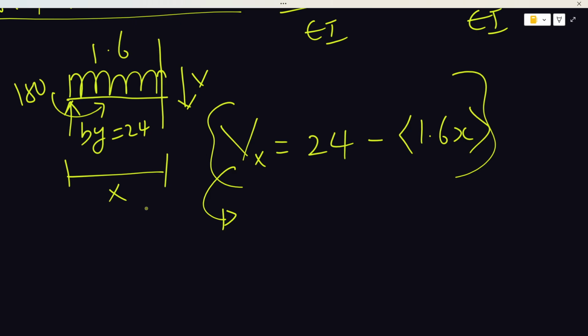So it means that we're saying, give me a position of x that would make my shear force equal to 0. What is the special thing about your shear force being 0? Your shear force being 0 is the place where your moment will be maximum. But how should I go through all that stress when I have my shear force now? Why can't I just put 0 in my shear force? Exactly.